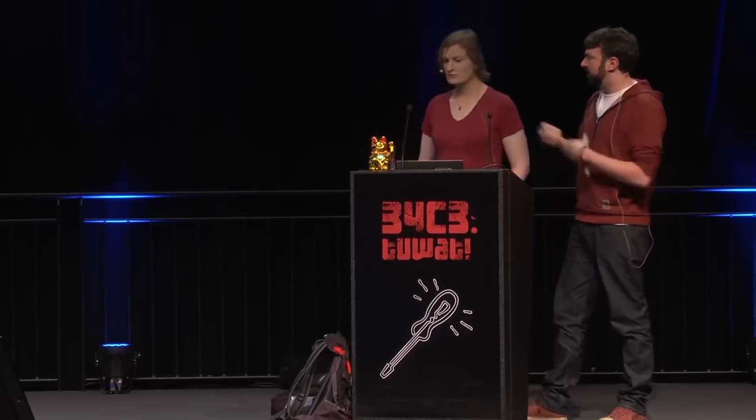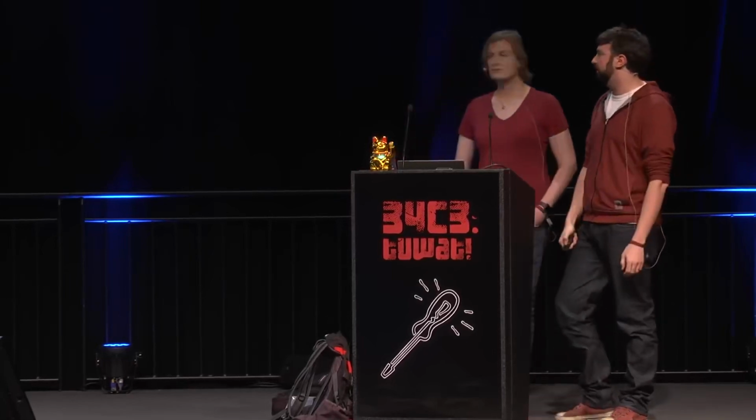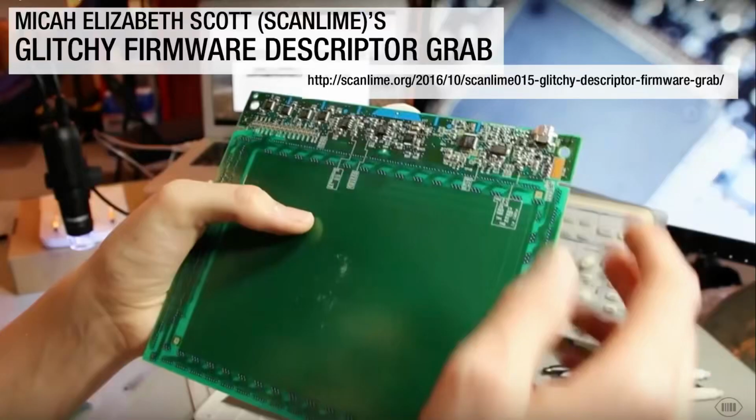And then these things can be used. The final thing is to then talk to the ChipWhisperer and trigger some output from it. This is a cool thing because you can take that trigger signal and trigger the ChipWhisperer to start doing its glitching process. Or if you want to, you can use that to drive the trigger input to your oscilloscope or logic analyzer. So you can use this as a source of debug information outside of glitching, even though that's not our main purpose. Really, this is a general purpose stimulus and triggering engine that we happen to be using for glitching.